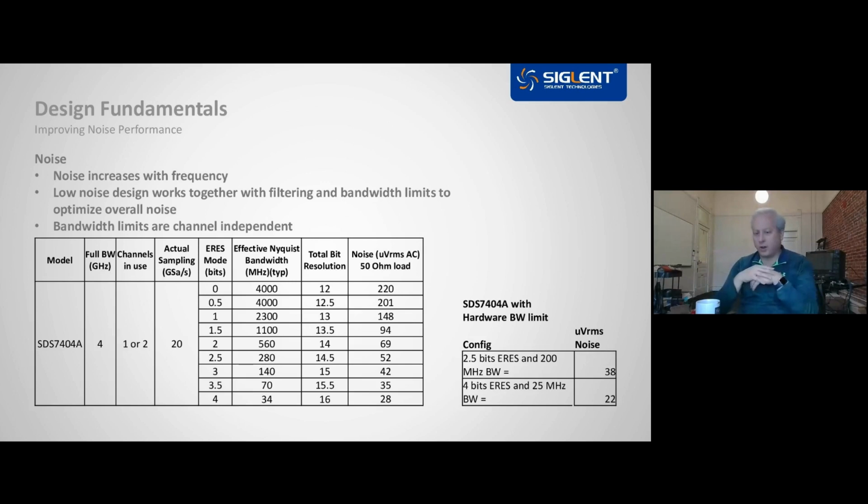When designing an oscilloscope, noise can come from many sources. Most important here are component selection and layout. They have a large impact on noise. Also, noise is strongly impacted by design outside of that main analog front end. So EMI considerations and power cleanliness make an impact. The important thing to remember is that designing a high performance oscilloscope goes well beyond just adding a new A to D with extra bits to your existing design. The best designs consider both key specifications as they relate to use cases, as well as overall design quality. And that starts with noise.